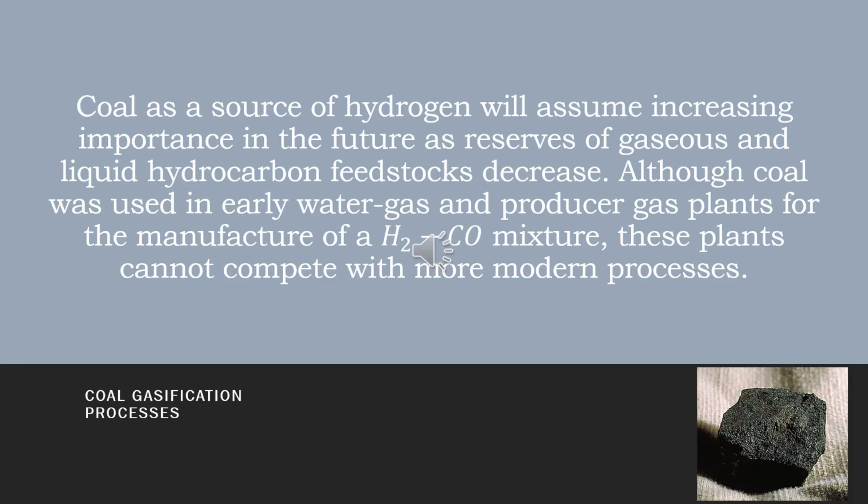So we have here the coal gasification processes. Coal as a source of hydrogen will assume increasing importance in the future as reserves of gaseous and liquid hydrocarbon feedstocks decrease. Although coal was used in early water gas and producer gas plants for the manufacture of an H2-CO mixture, these plants cannot compete with more modern processes. The gases produced require the water gas shift conversion and subsequent purification to produce high purity hydrogen.